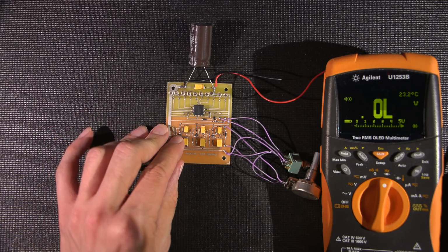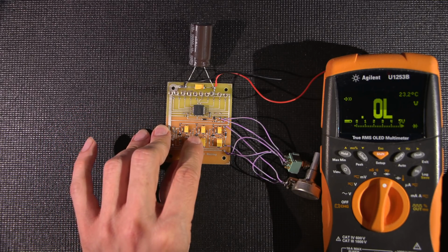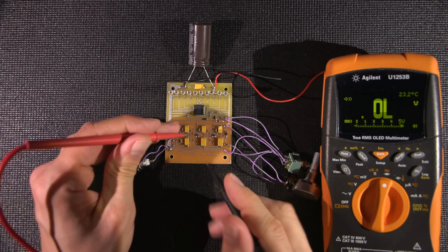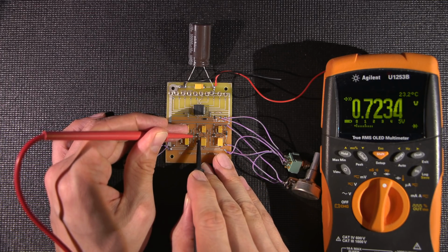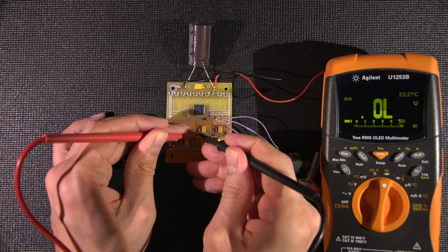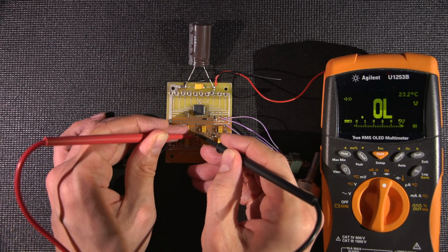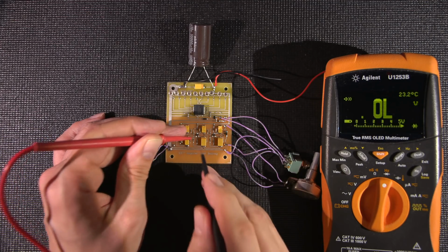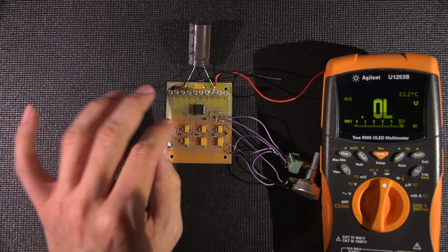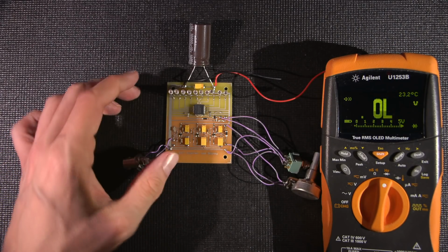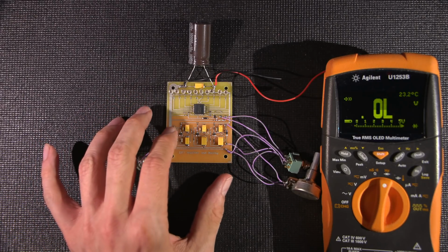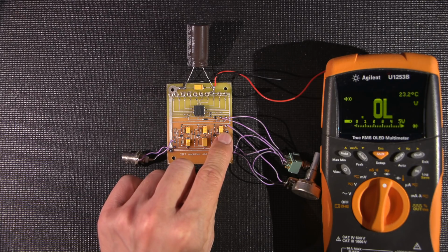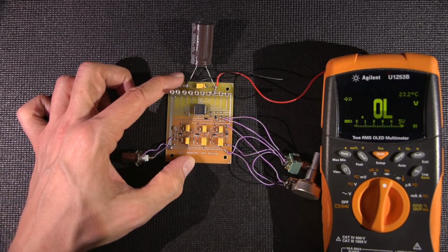So we now know that we have an NPN transistor here, and we would do that all the way along. So if we didn't know this was an NPN transistor, again, I would take this and put this on the base, go here. You can see we have what looks to be like a diode, I should say, there, and on the top, again, the same. And we would go along and check that. And then this way we can verify that we're dealing with all NPN transistors. So at this point, we know that these two are NPN transistors, and again, we would redo that check here and we would realize that we have 3 NPN transistors.